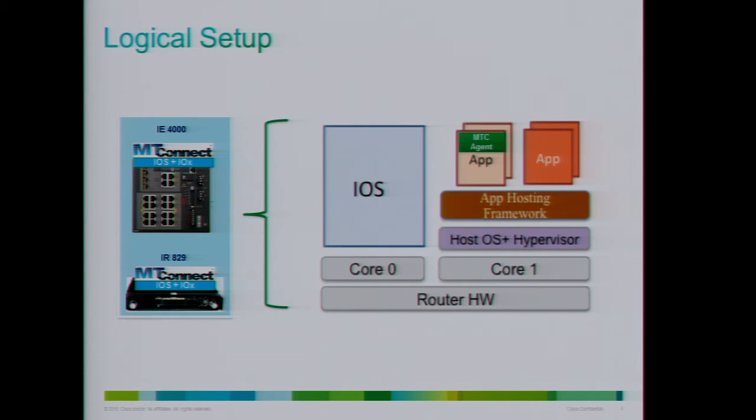And while you brought up this topic, I just wanted to mention one more thing: the serial interface. There are a few machines which only run serial. They don't have Ethernet capabilities. So even serial interfaces are supported with the IR829 because that runs a different protocol called Modbus. I'm not sure if you're aware of it, but that's another protocol which can extract your data from the machine and give you information about what your machine is doing. So that is also something it can run.